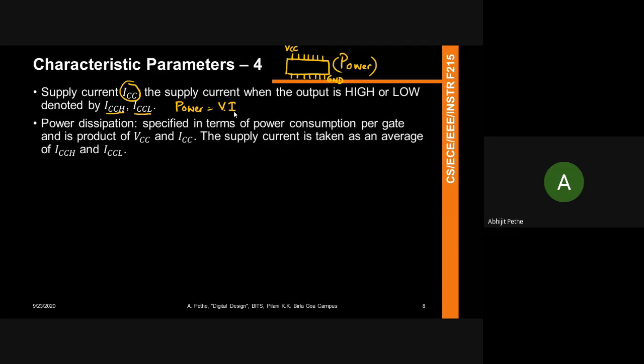And therefore, the other thing I just alluded to would be power dissipation. So we normally also look at what is known as power consumption per gate, in addition to ICC, meaning how much power is consumed per gate. Again, this defines your overall power envelope.